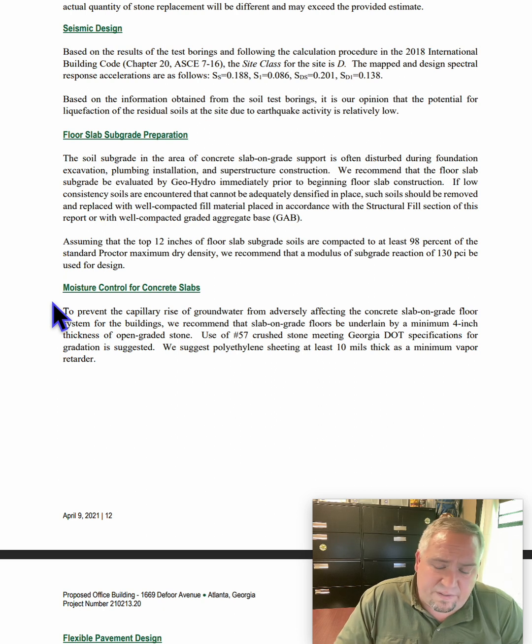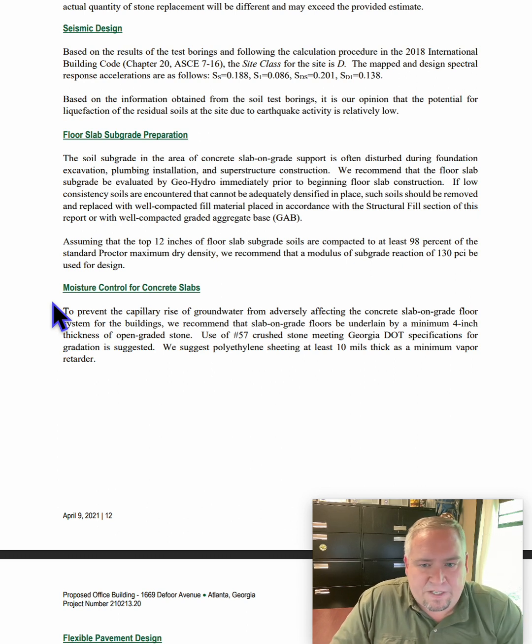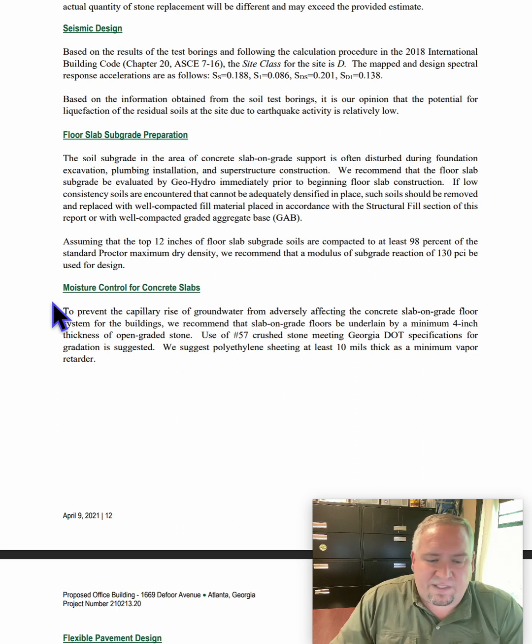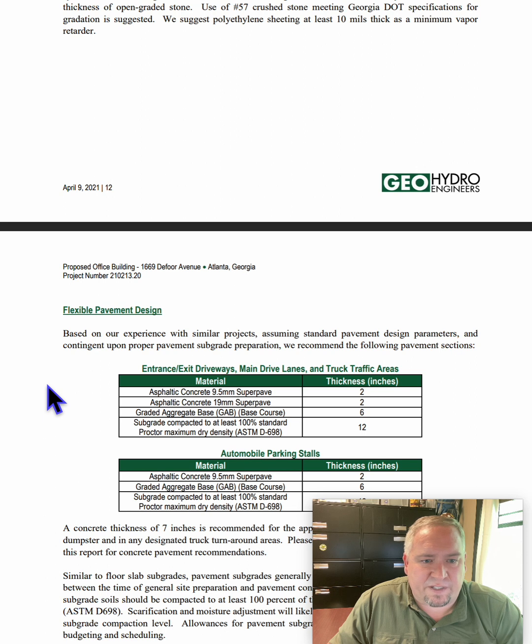In certain sites around here, we've had to make sure we haul in 57 stone and plastic for radon. It's a gas that comes out of the soil. It's in high rocky environments. So moisture, any of these things, they're going to start being important for us to understand.